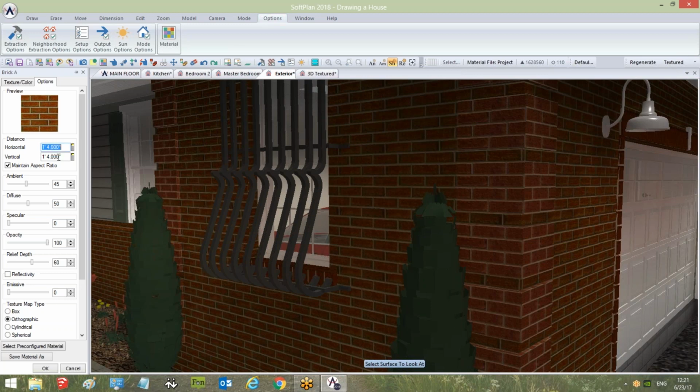So at the beginning, we have our horizontal and vertical size, and so that's the size of the image that's repeating. And so you can see here we have 6 courses of brick. If we did the math here, the standard height for brick typically is about 2.6 inches. So the entire height of this would be 16 inches, or 1'4". And then for the default or standard length, we have roughly 8 inches. And so times that by 2, we again have our 1'4". So that's where these sizes come from, just so that we have a texture that accurately represents what's going to be there in the finished product.